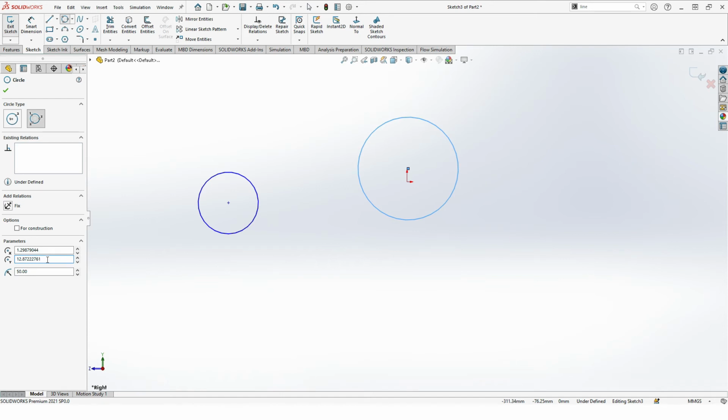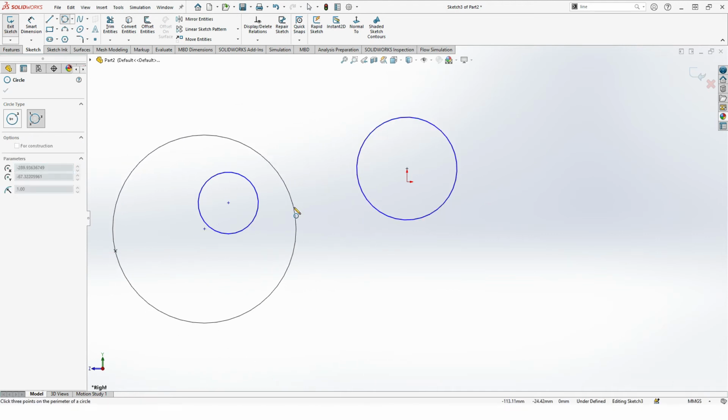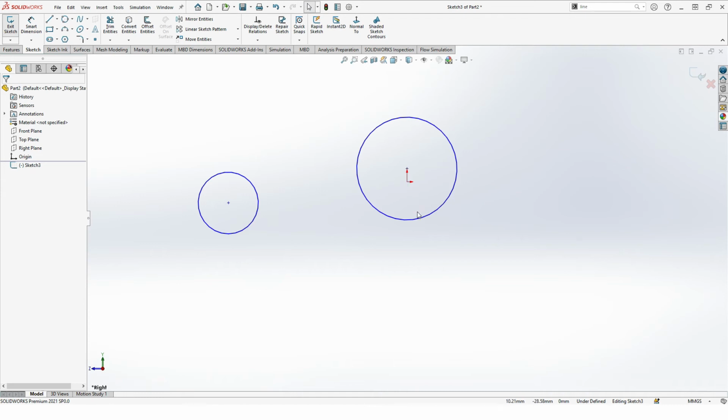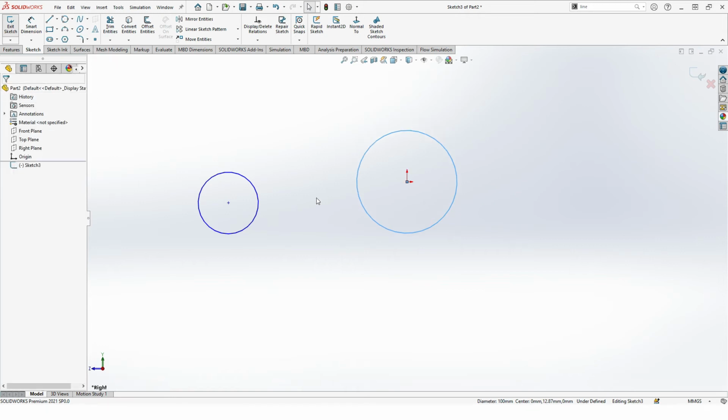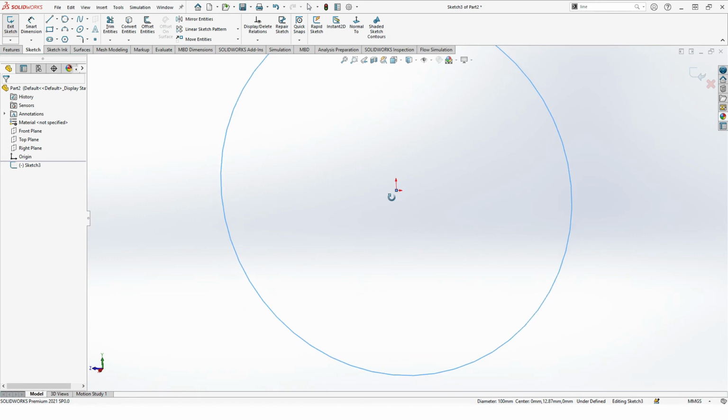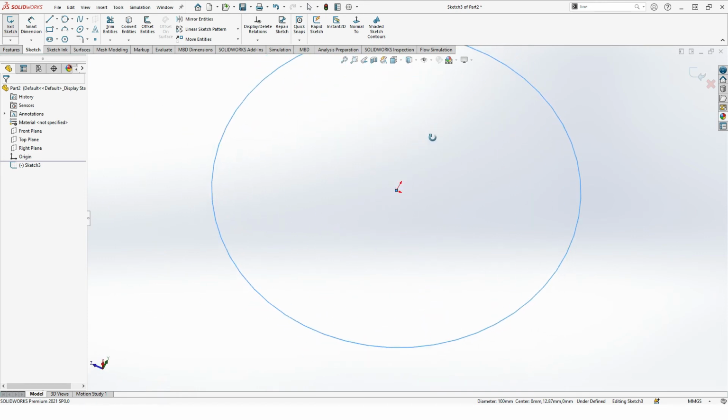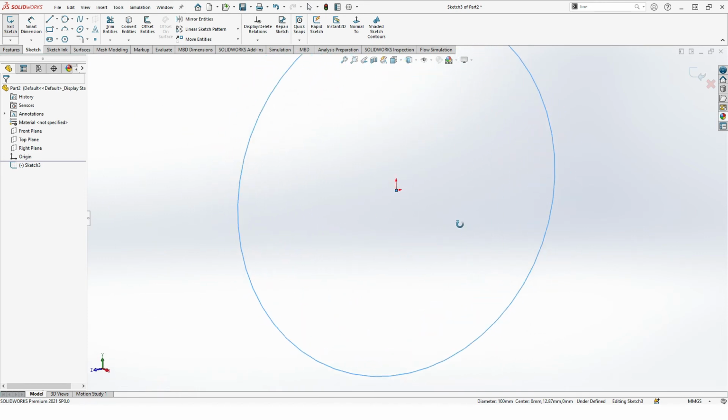And we can give the value here, so from the x-axis how far it should be. If we give 0, see, it just came to the center. Just click this, and if we give this value also 0 and click close dialog, the center of the circle is exactly on the point of the coordinate origin.